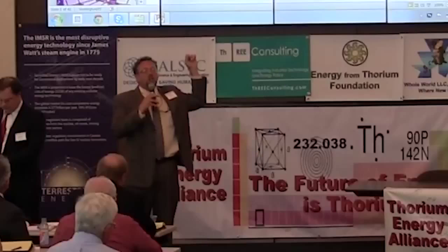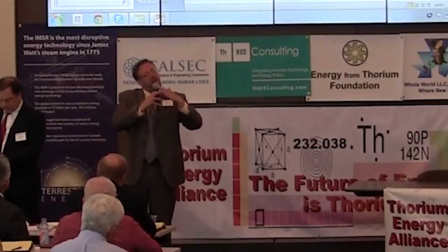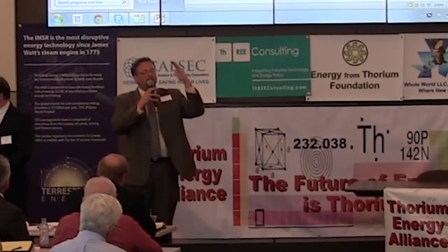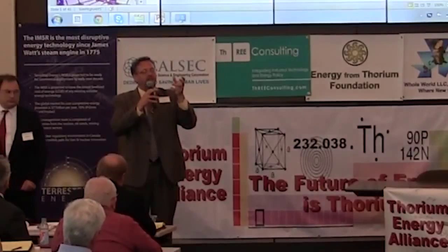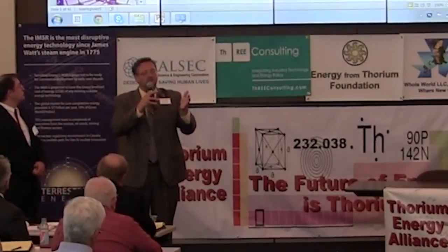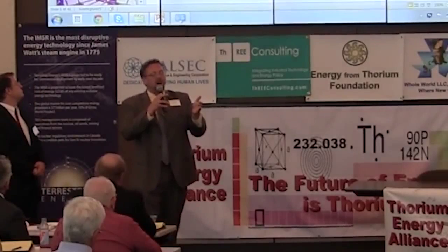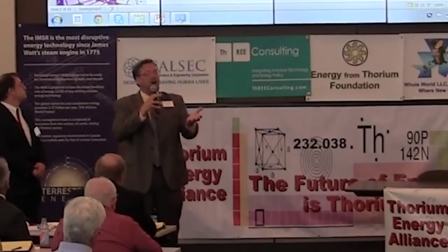I would suspect that the high symmetry of the thorium dioxide, which is cubic, which is Fm3̄m, shouldn't slough off because you're not going to have a lot of shear planes. As Kim Johnson has suggested, adding a little bit of other metals, in other words, not more than 400 to 800 ppm, for example, such as niobium, you would retard oxidation entirely, or at least prolong the process dramatically. And so that's just one example with respect to water.